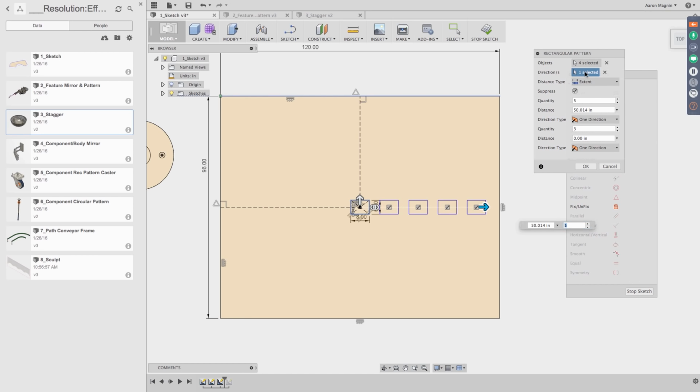I can go back up to these directions options that are right here. So I went back to this dialog here, and I selected within here. And if I wanted to go up and down as well to fill this face completely, I can select an additional edge to orient some other items. Now, when I first select that, you don't really get a preview, and that's because by default, when you select it, the distance spacing there is at 0.